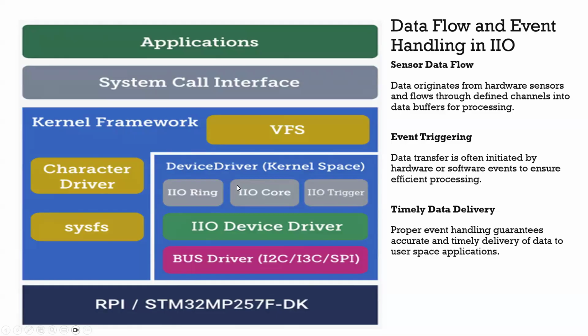Because the user will be seeing the device through the IO, you can say that your device has four channels, but physically there won't be four channels existing. There is only one channel existing. It is completely user programmable. When you are writing code for the IO core, you'll be writing some minimal code where you create the different channels. Once this driver is ready, those channels will appear to the user space.